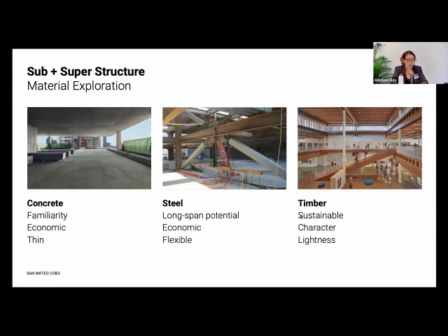So to answer the question from the room, at SOM, we explore all materials on every project. We love iteration. We love research because we're fun like that. And so we challenged ourselves to look at the entire structure in 3 different materials. We not only designed the engineering of the structure in all 3 materials, we also had them cost estimated to confirm what the real delta was, perhaps to challenge and disprove: does low embodied carbon have to be more costly? It doesn't, is the answer.